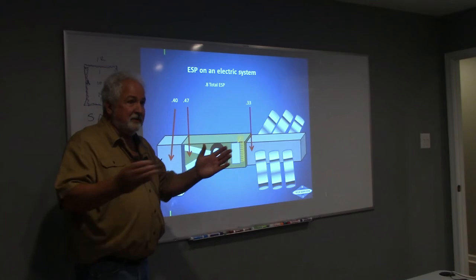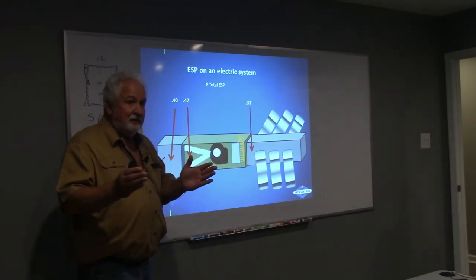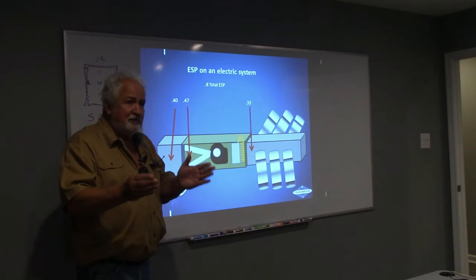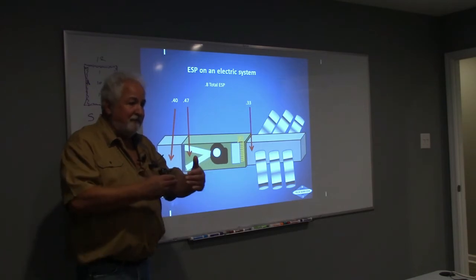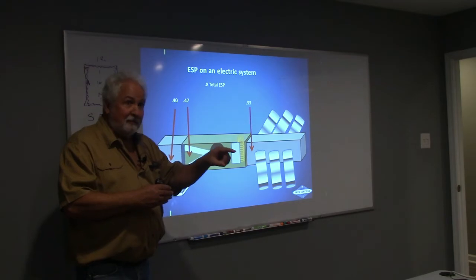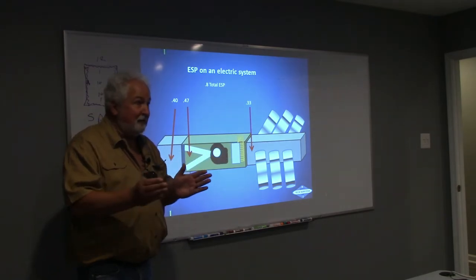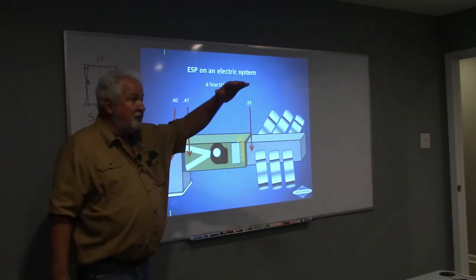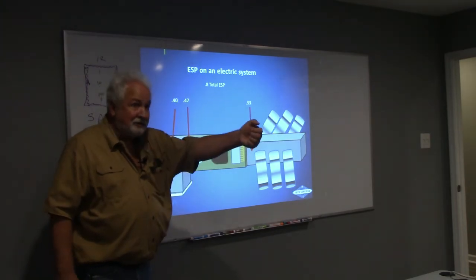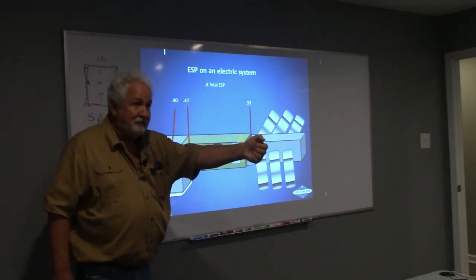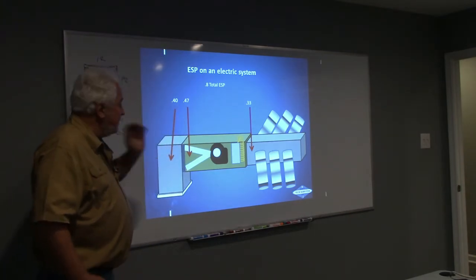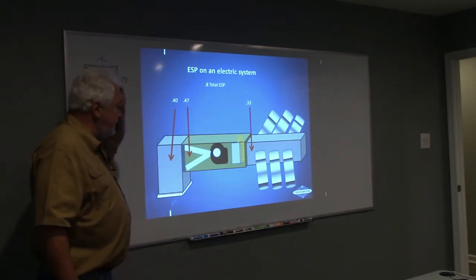So really 2x6 is 16-inch centers, right? Yeah. So that means it's 14 and a half inches between there. So I got 14 and a half by 5 and a half. So that's what we're going to size that for, 5 and a half by 14 and a half, not the 30-inch filter that they've got in there, because this is where it's plugged down on my hose, yes? Okay, cool. All right, so we see that the problem's on this side, yes? Good, all right. So what is my total external static?